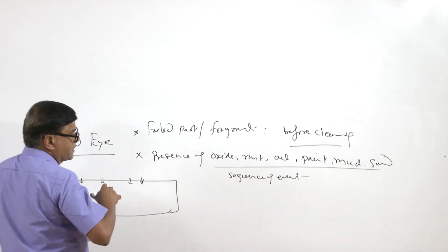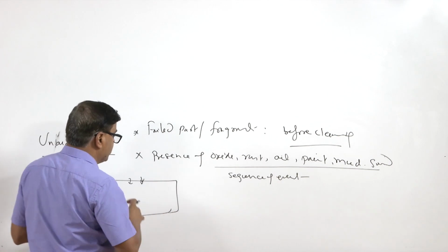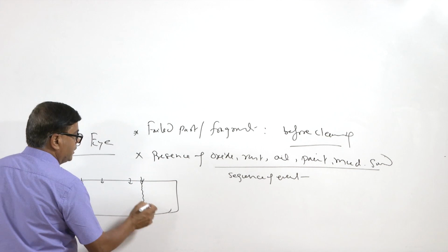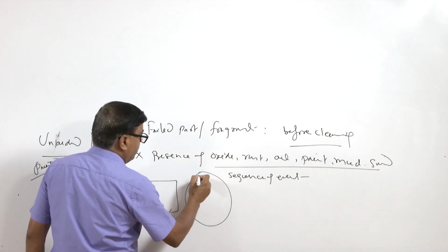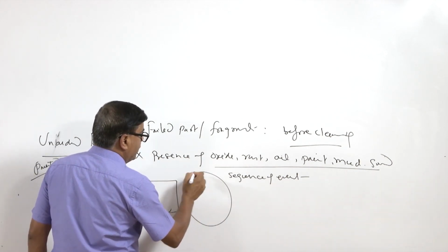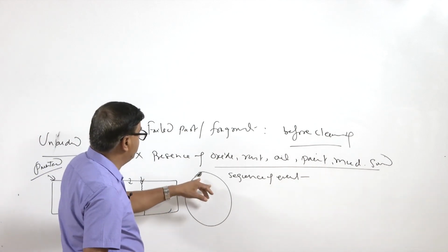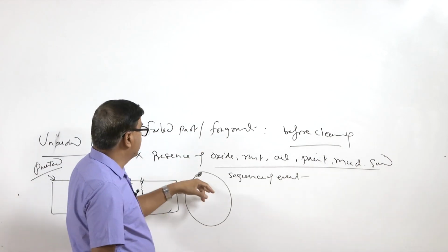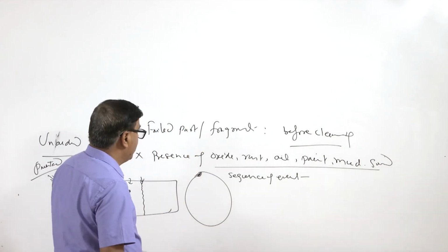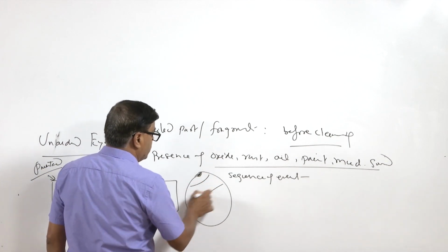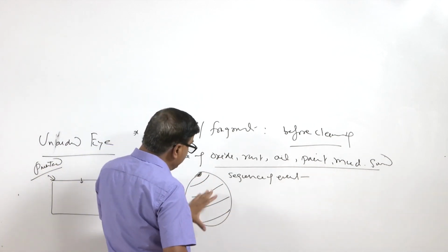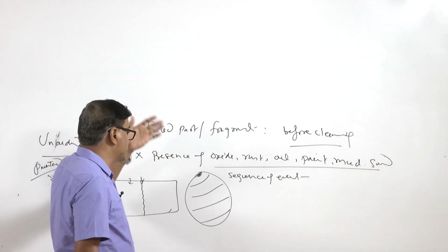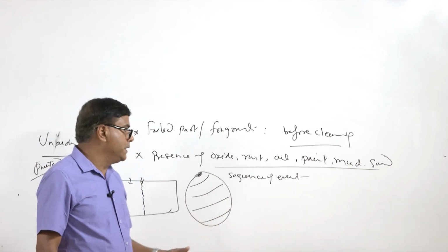After say 6 months or 1 year, if this shaft fails from this location, it will show the presence of paint over this particular area. So, this will suggest that the painting was done about 6 months or 1 year before, and the crack was present since then, and thereafter the crack has grown gradually.